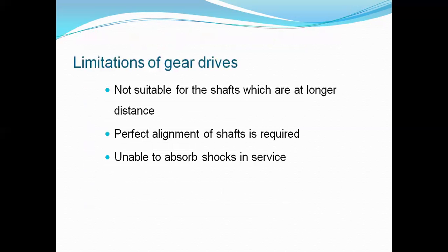Coming to the disadvantages, it is not suitable for shafts which are at longer distances. For longer distance power transmission, we go to belt drives. So gear drives are not suitable, and perfect alignment of shafts is required. Here, two shafts with mating gears are connected with each other, so the alignment problem is high. It is also unable to absorb shocks while in service.